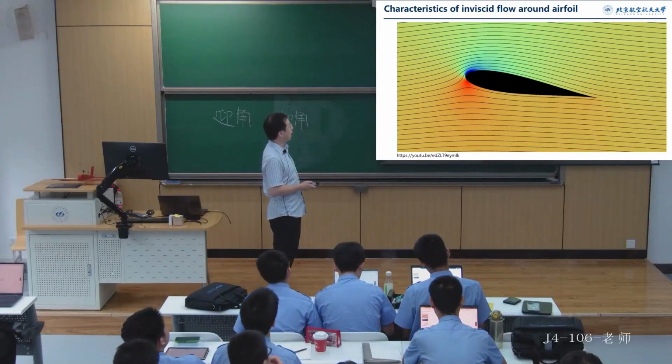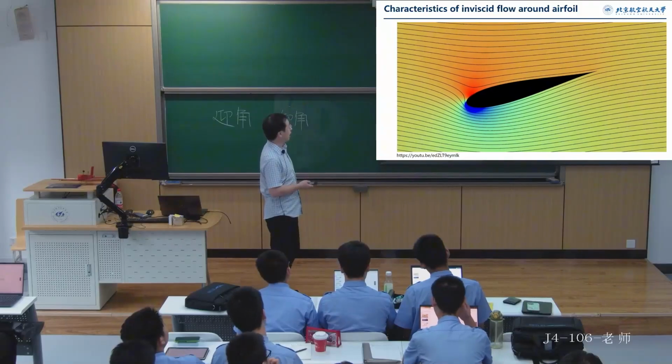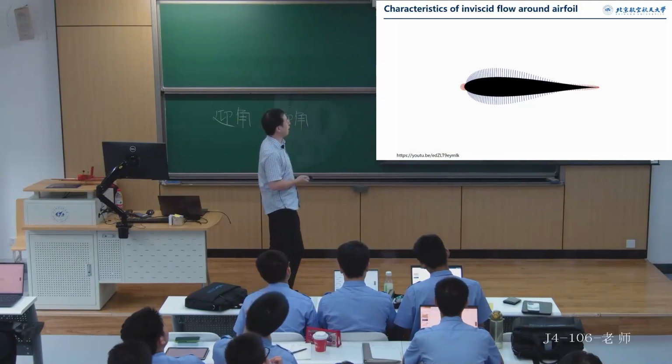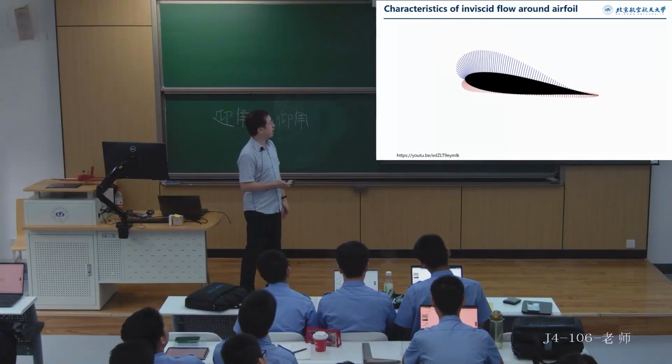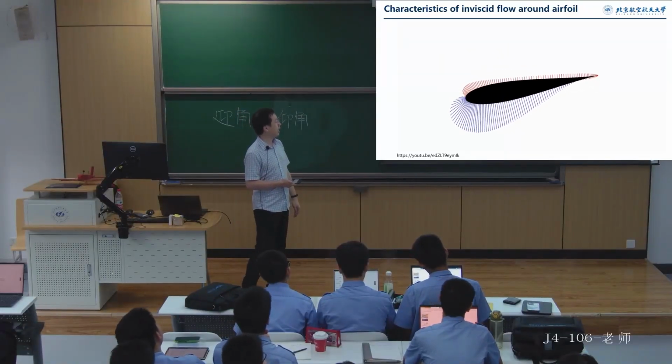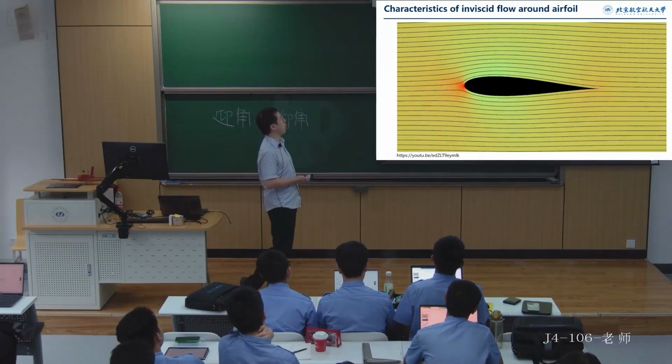This is the case with a positive angle of attack. This one is with a compound angle of attack. What we're showing below is the distribution of surface forces after the change. The length of the lines represents the magnitude of the force. The red lines indicate pressure, and the blue ones, we refer to them as suction. We'll explain later why it's called suction.